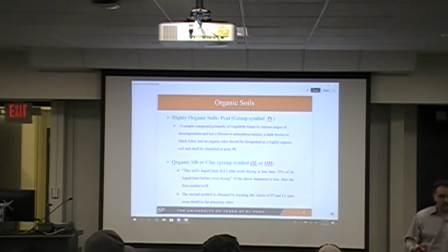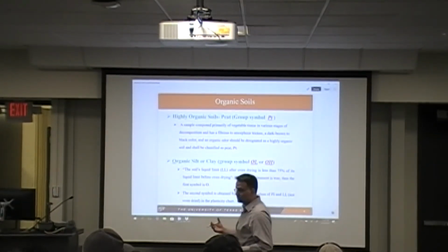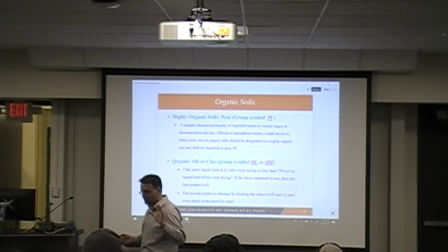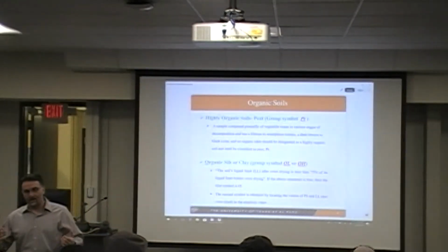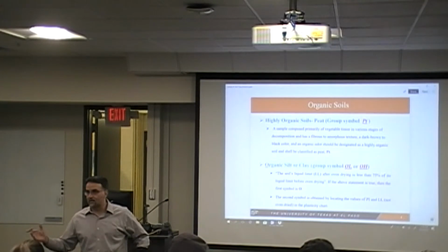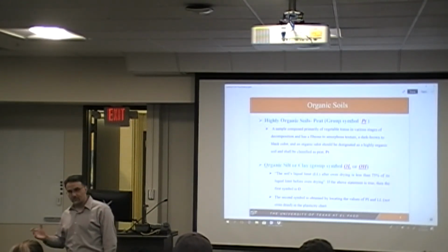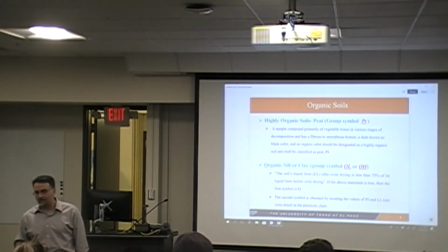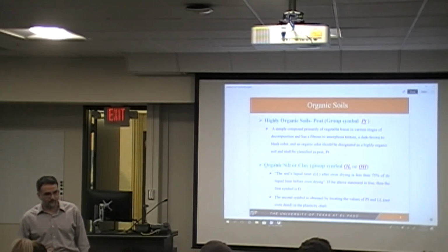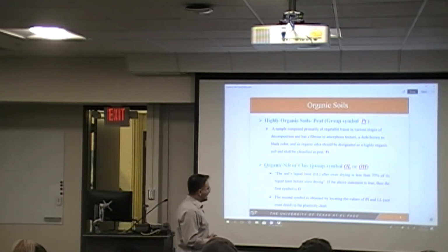So the way that you have to identify that is based on running the liquid limit test of two samples. One, put it in the oven for 24 hours and then run the liquid limit test. And the other sample is for materials that are not subjected to oven drying. If the difference is more than 25%, essentially that material will be considered as organic material. Right? So that's basically what the definitions entail with regard to this organic material.